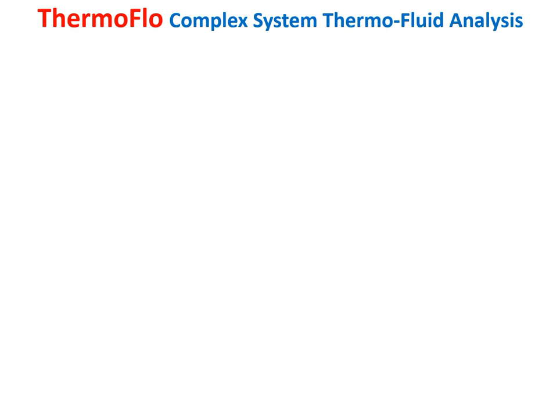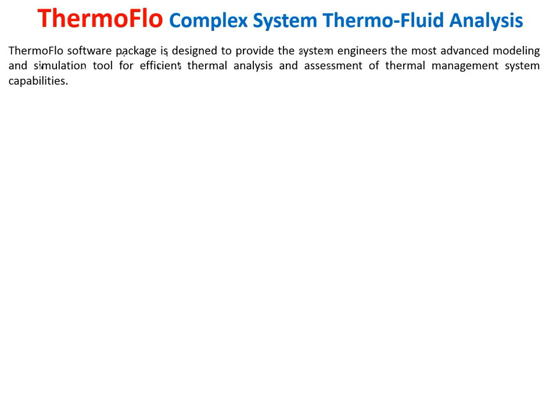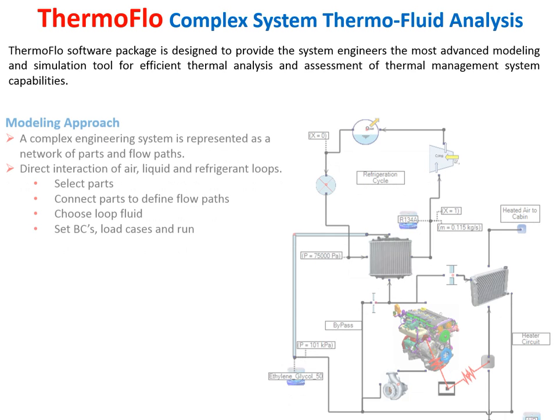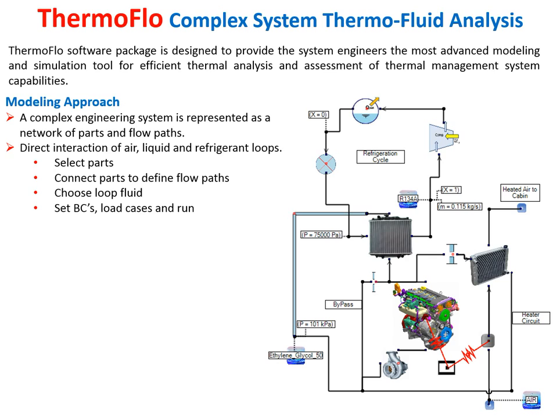ThermoFlo is an advanced modeling and simulation tool for analysis and assessment of thermal management system capabilities. In a ThermoFlo model, a complex system is divided into parts and flow paths with direct interaction and coupling between air, liquid, and refrigerant loops. To construct a model, the user selects the parts, connects the parts to define flow paths, chooses a fluid for each loop, then sets the loads and boundary conditions, and runs the simulation.